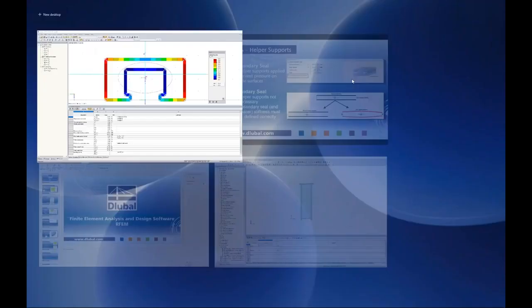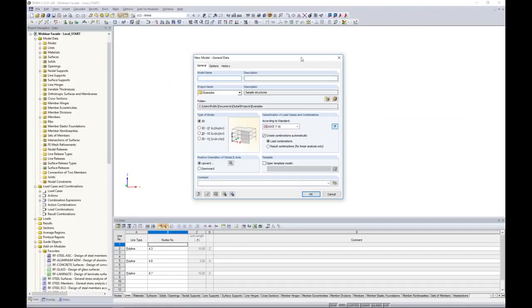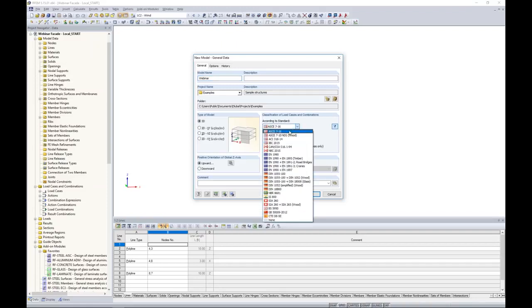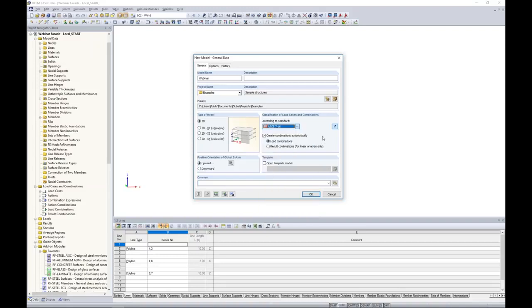So now changing programs here, we'll go over to the program RFEM. To begin with, I need to create a model name. For this one, we can call it webinar. Now, the type of model is 3D. The load combinations, this is where we can set the automatic load combination generator according to the ASCE 7 2016. We have the NBC 2015, as well as many other international standards.